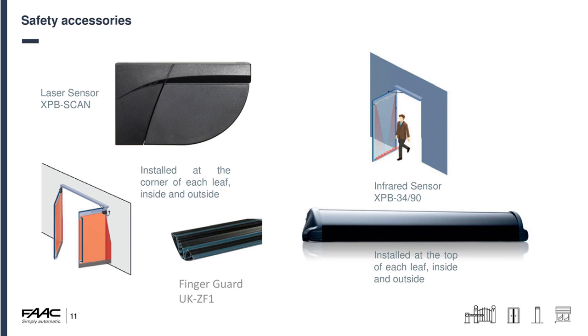The way around this to get rid of using all of those would be to use the flat scan. Now the IPB scan fits into the top corner of the door, it covers the hinge area, so no finger guard required, and maps out, like I said, 172 laser points and covers the opening and closing faces. Very discreet, very nice in its application, not intrusive on the door. You can actually paint these up to match the colours if doors are painted into a specific colour.